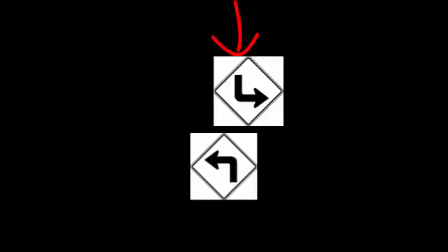The first left turn leads the opposing through movement, while the opposing left turn lags the opposing through movement. Lead or lag operation can have important benefits for a system of signals that have been coordinated to provide smooth flow along the main street.